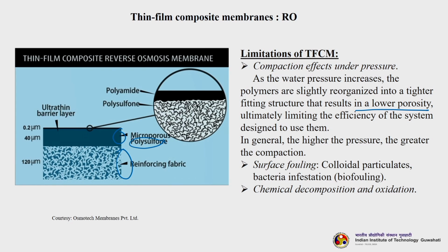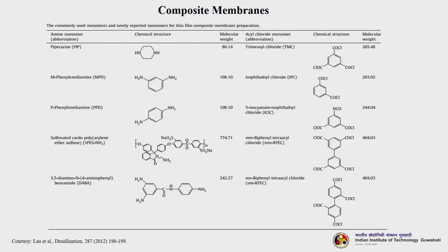Another problem is surface fouling. This comes from colloidal particulates and bacterial infestation resulting in the biofouling characteristics of the membrane, and then chemical decomposition and oxidation. This all depends upon what type of solutes the particular membrane is handling. So, have a close look at this particular table.